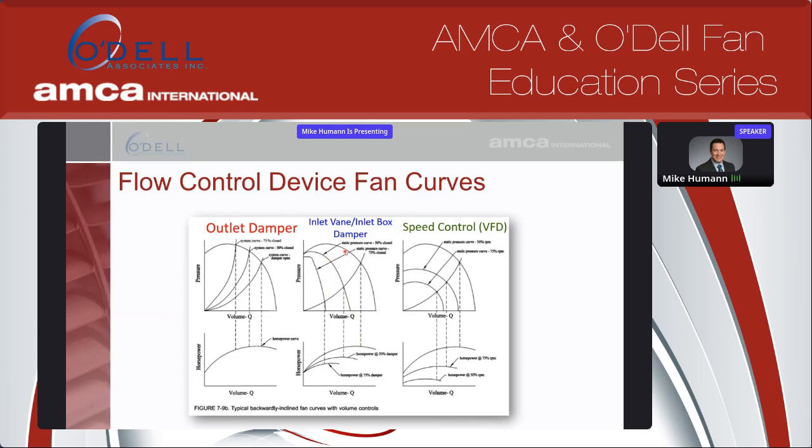One of the benefits of the inlet vane type damper or an inlet damper is you can maintain static pressure here. You'll see with the VFD, you don't have the same static pressure capability. You don't lose as much of it with an inlet vane damper. So that's really good for situations where you need a 4 or 5 to 1 turn down. You're going to want to look at an inlet vane damper to help you control that fan.